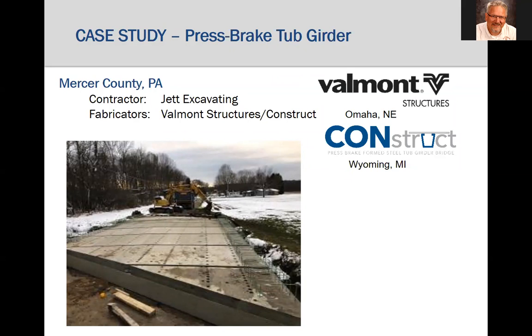Due to constraints on this project site and the equipment lifting capabilities of the contractor, it was determined the most efficient method of installation for the new superstructure would be using the field assembly method, putting on full width precast concrete decks with grouted shear stud pockets for composite action with the tubs.